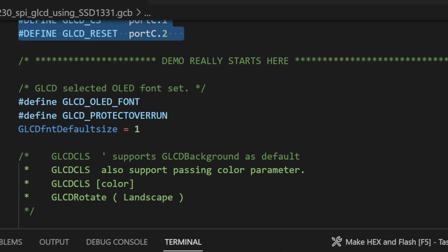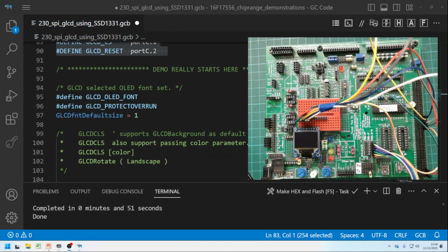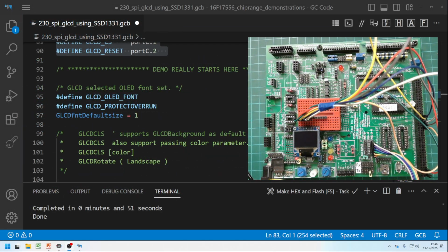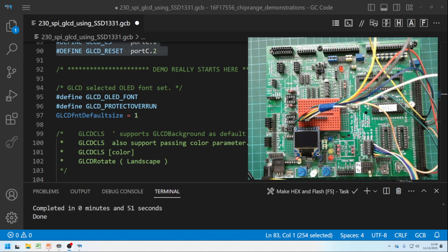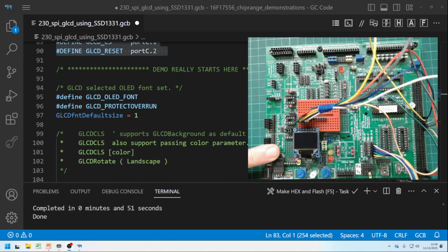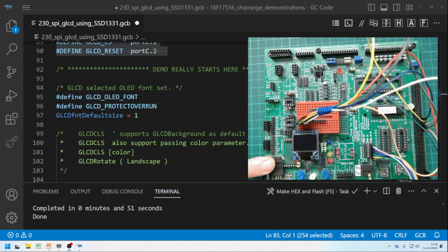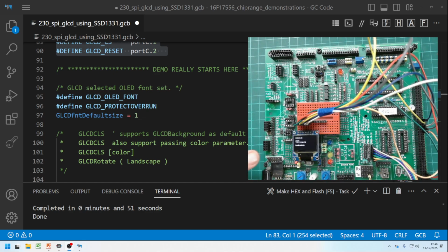Let's have a look what's happening over here. It's black. Have I got any power in the board? Now, I showed you that that line was wrong. I showed you that I was setting A.4 to 0. So I'm going to power cycle the chip. And voila, it burst into life. It only burst into life because the PPS ports are now free. They're set to 0. You can see it's doing stuff, okay?